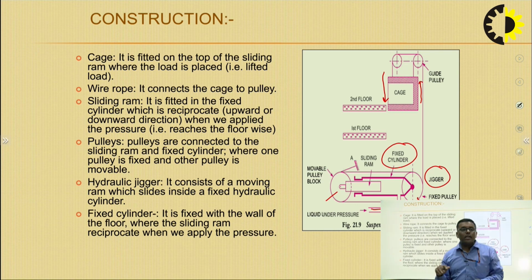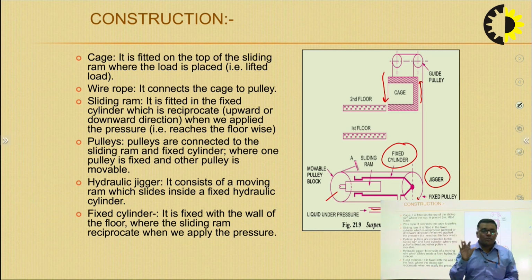So these are the two hydraulic applications which I discussed today. One is the hydraulic accumulator, another one is the hydraulic lift. Hydraulic accumulator is the temporary store of hydraulic energy. As and when it is required by any hydraulic application such as lift, crane or press, it will be delivered from the hydraulic accumulator. And the lift is nowadays a common feature everywhere. There can be two kinds. One is the direct hydraulic lift, another one is the suspended type of hydraulic lift. And the basic principle behind it is Pascal's law, which is very clear to everyone.